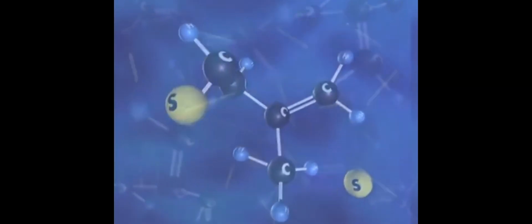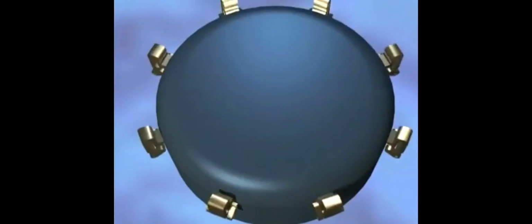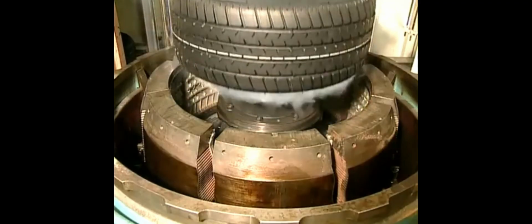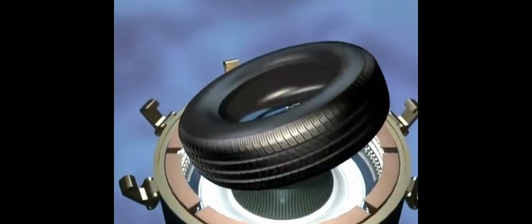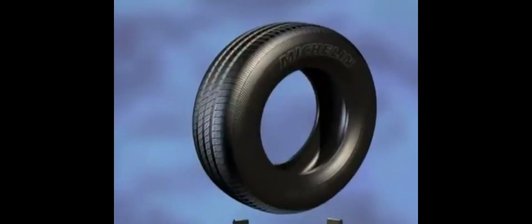This curing, or vulcanization, chemically bonds the rubber compounds to the steel and fabric cord reinforcement components. During this chemical reaction, the tire goes from a plastic to an elastic state. Sometime later, the transformation is complete and the tire emerges from its metal shell. The tire has been given its final features and finished shape.